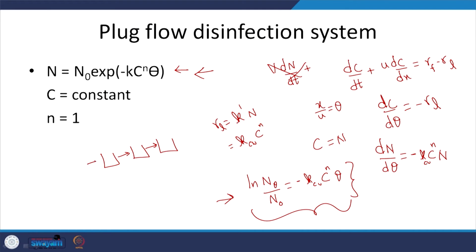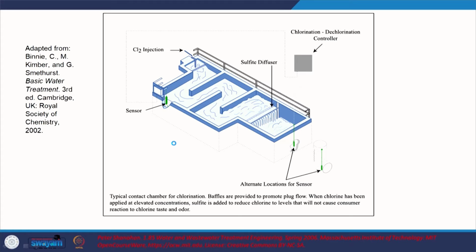This is especially the case with plug flow reactors in the context of disinfection, let's say, right? Why is it? Because if I'm trying to bubble through ozone, which is a strong oxidizing agent which can degrade the cell walls and thus lead to disinfection, the system will typically behave like a CSTR. So to be able to approximate or achieve a plug flow reactor system, I will have it in series, or there are different ways to go about it with baffle walls and such too. So that's one aspect to keep in mind, right?